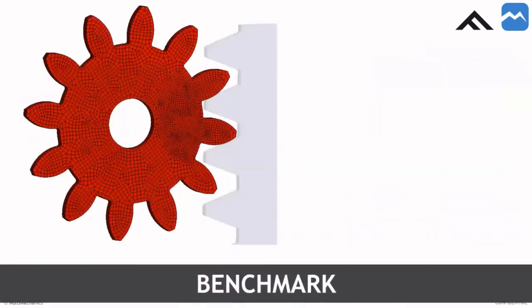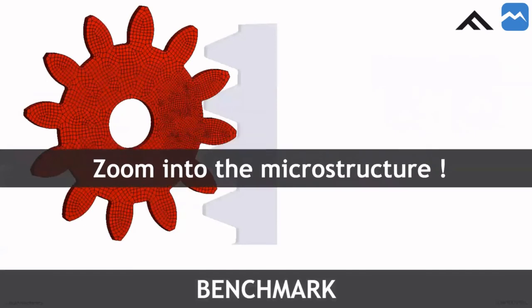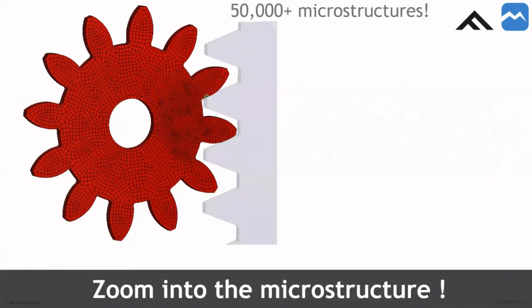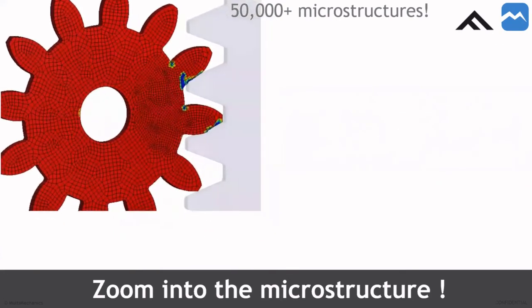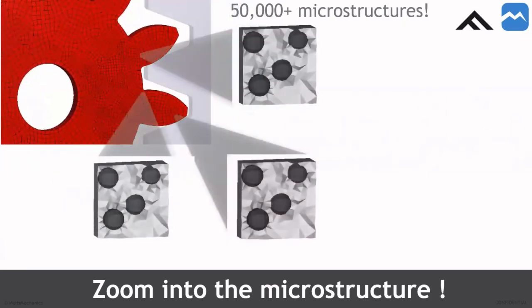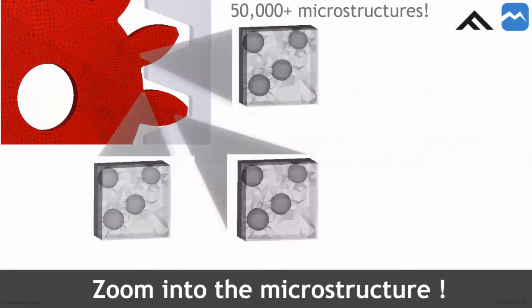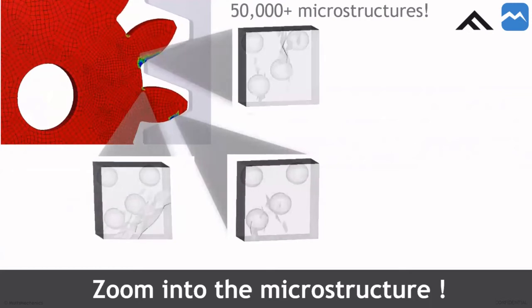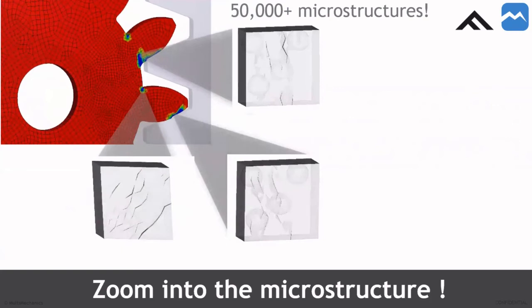When I say fully coupled, there's a few simulations we're going to show that really help illustrate what we mean by that. Right here, we have a gear and it's being loaded. The blue represents stiffness reduction. So that's basically the elements that are beginning to fail. Now, if we zoom into this microstructure, we're going to look at 3 different areas. So you see the same microstructure, but as we begin to load it, you start to see some cracking develop in different ways. This is just a way of showing that every single element in this global gear part is being represented by another microstructure independently.